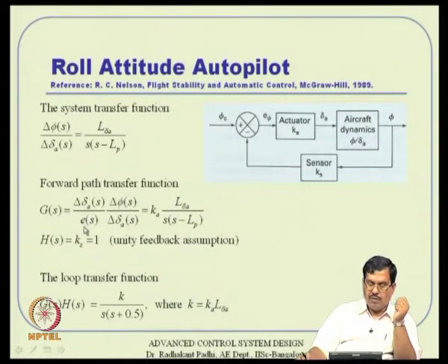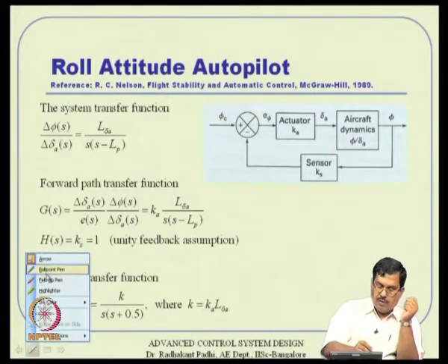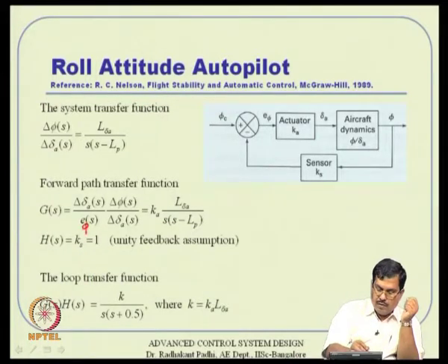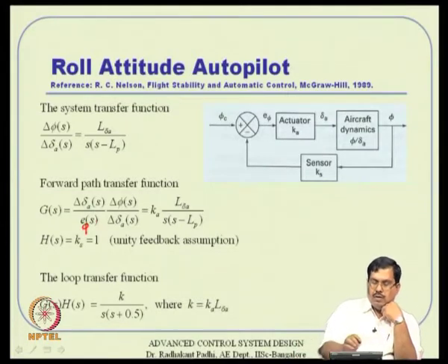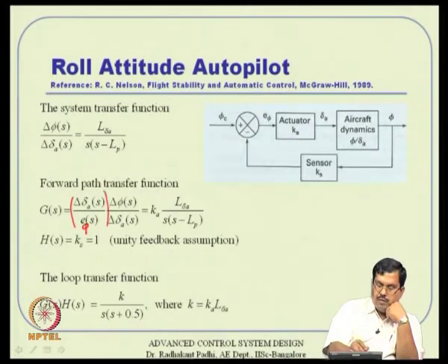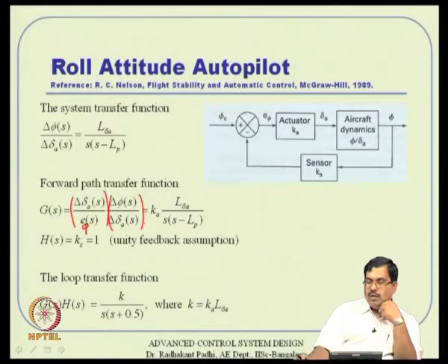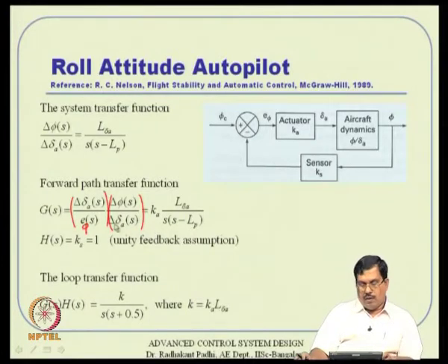This is E phi probably. Okay. You can put that, delta a to E phi, and multiplied with delta phi to delta a. This to that transfer function, delta a to E phi, and then delta phi to delta a. So, if you multiply these two transfer functions, you will get it. And we are assuming that the Ks is 1. So, we essentially end up with a unity feedback kind of situation, where the analysis becomes easier. Any other gain is also fine.